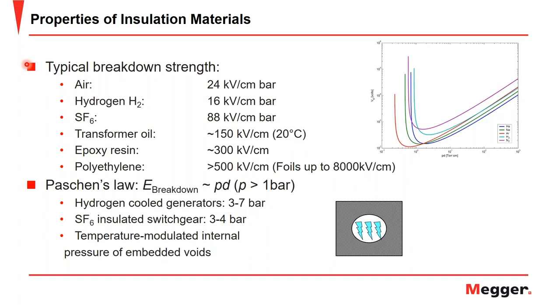And these gases, or this medium, as I mentioned when we were talking initially about the different insulating materials, cause different characteristics of PD activity. So the rise time in nitrogen, which is an electropositive gas, is much slower than that of SF6 or C5PFK, which results in a more narrow measuring bandwidth, whereas SF6, which is an electronegative gas, would have a larger bandwidth.